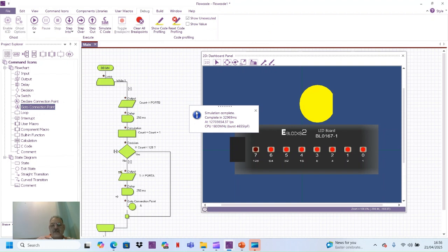This particular logic you would need once you are going to make a program in your exam where you have to do some process for a particular time. So you use the counter, and then after a certain time, if you make the delay as 1 second, then it's going to be 128 seconds. The program will run for 128 seconds. That means if you count up to 120, then it's going to wait for 2 minutes. That is 60 seconds for 1 minute, 60 seconds for the second minute.